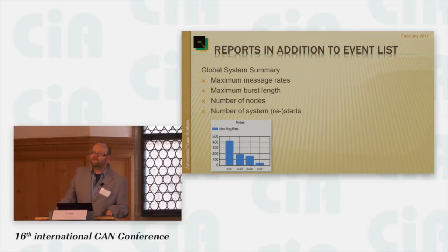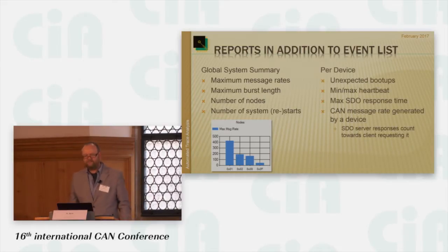And we said, because there's so much communication with the direct connection, SDO connection, there needs to be a certain limit, and somewhere in the standard you'll find the number. We called it a safe plug-and-play device. A safe plug-and-play device may not cause more than so and so many messages per second. And there's then an exception, we defined something higher. It was then a high bandwidth safe plug-and-play device.